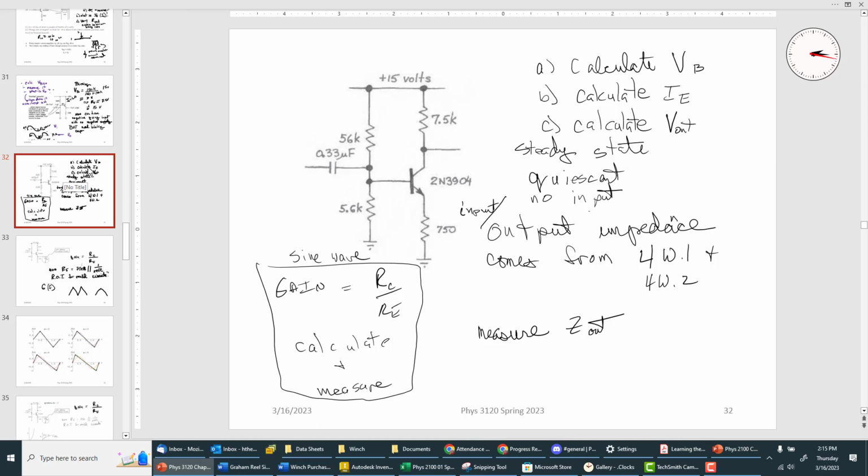Yeah. So it asks what should the output impedance be, and it says try to measure it. Right. You can do the same with the input impedance. What's its low frequency 3 dB point? That means you pick a certain capacitor. You can measure the 3 dB point, and that'll give you a clue because it's an RC constant, but